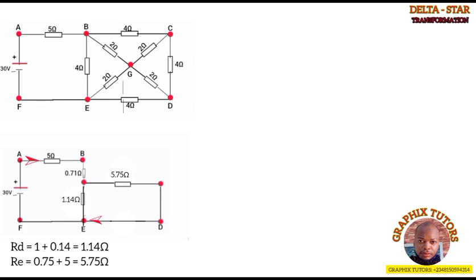Now, what do you notice? At this node here, let me call it node Q, there's a split. The current that will be flowing through here will not be the same current that will be flowing through here. That is, the current flowing through 1.14 will not be the same current flowing through 5.75 because of that split, making 1.14 and 5.75 parallel to each other.